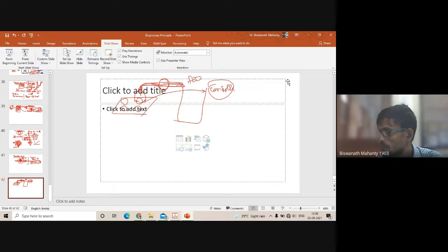What is the reason when we need it? We need it for those fermentation processes, particularly anaerobic, where there is a high amount of gas formation, for example, carbon dioxide or methane. If we don't know how much pressure is there, we will not collect it, right? If I see high pressure, then I will open the tap and collect the gas. If I do not measure it, we cannot have any control on this. This is the first reason.